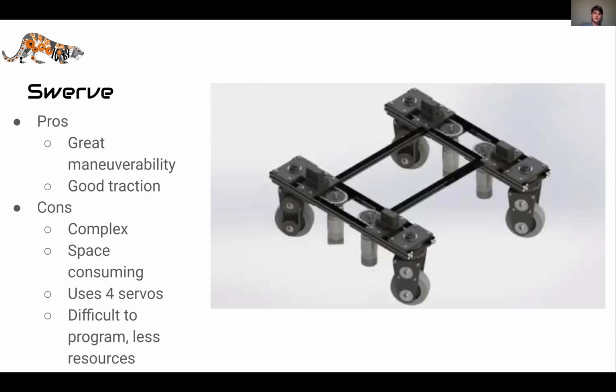It also uses 4 servos in addition to those 4 motors. We were talking earlier on the H-drive about how you want to pick an efficient method that uses the lowest amount of motors. Servos aren't really as valuable. We don't usually come terribly close to our servo limit, but it's just something to keep in mind that you are using 4 of your servo slots on your drivetrain. And again, you do get more than 8 servos, but it is just something to think about.